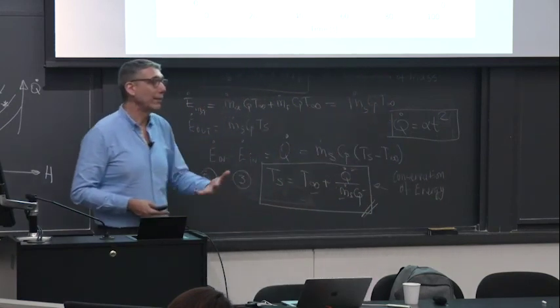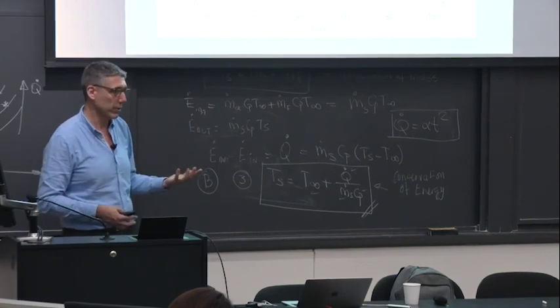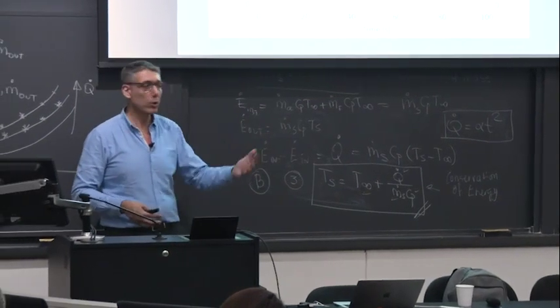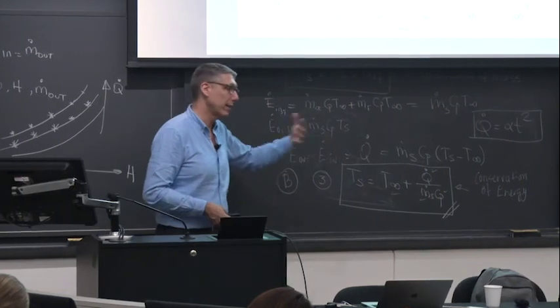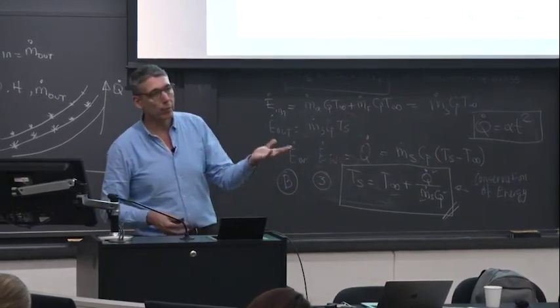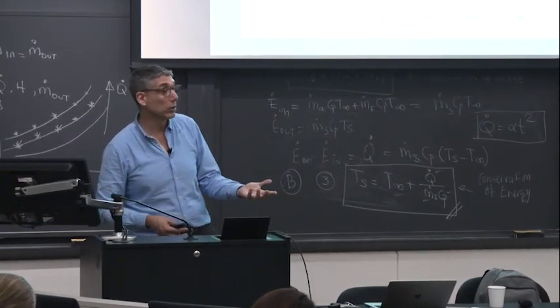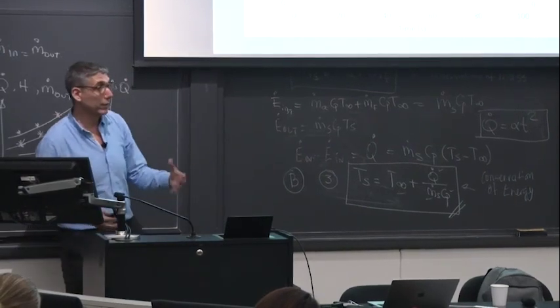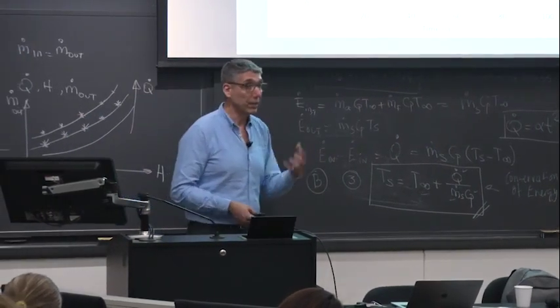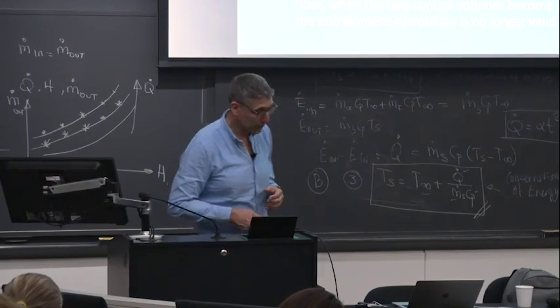That code will have a library of entrainment functions. So if your fire is in a bookshelf, you shall use this equation. If your fire is on the floor, you shall use this. So people have run experiments with a number of different solutions, and you have a whole library of entrainment functions, okay? Because that's what you're depending on.